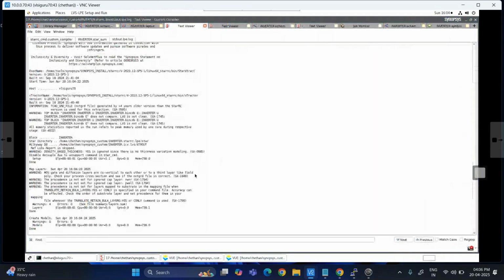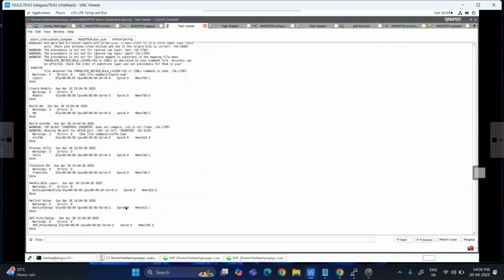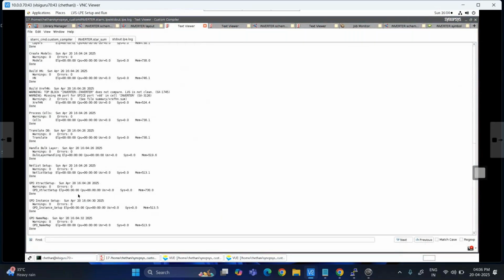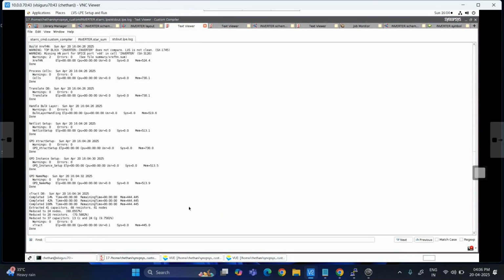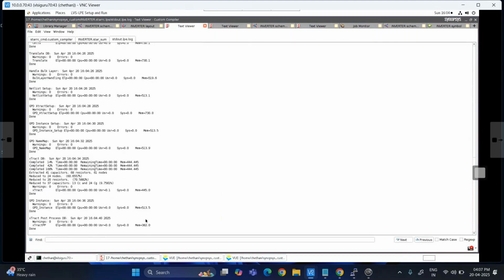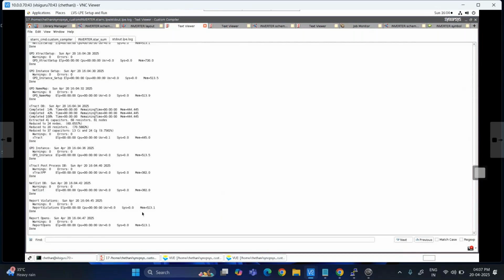In our design, a few DRC errors and LVS errors are there. After cleaning those two, then you can go for LPE extraction. Now the extraction is done, but you won't get the correct output because the pins are not matching. So this is how you can extract the LPE.